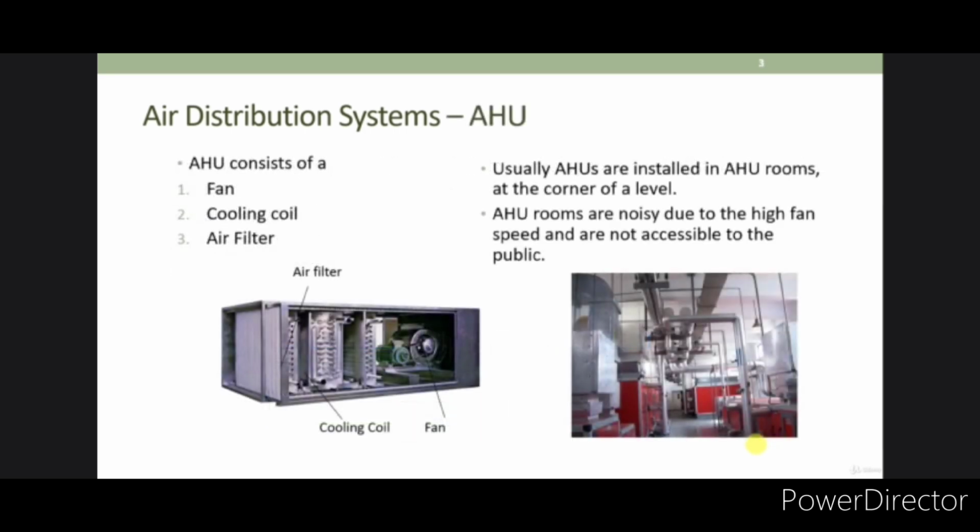So this is a typical looking AHU or air handling unit. So in front here, there is the supply air fan. And usually the supply air duct is over here. So cold air actually is being pushed out from here and goes to the area that you need to cool down. Alright, and in front of the air fan, there's the cooling coil. Okay, so air will actually get treated over here, either cooled down or heated up.